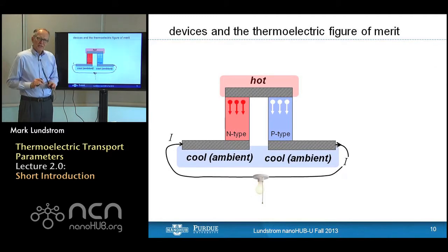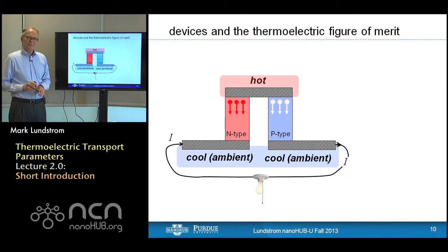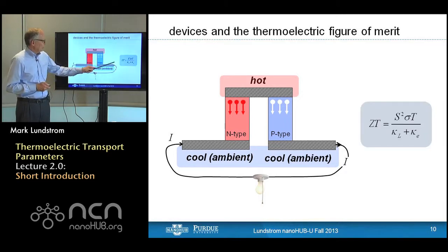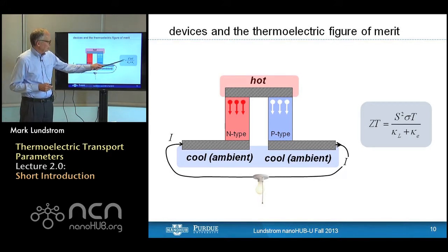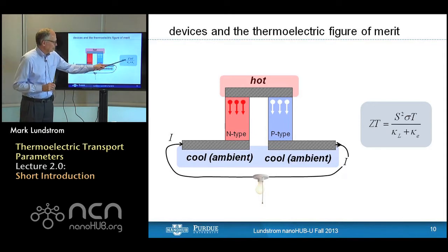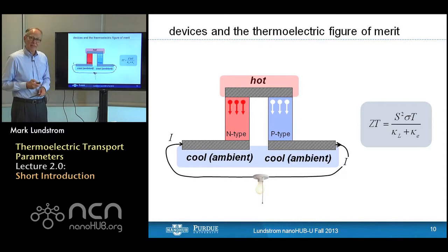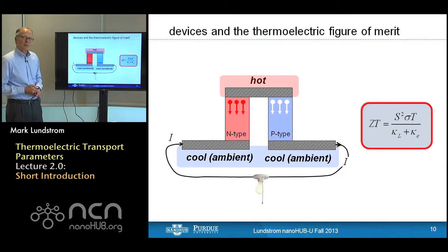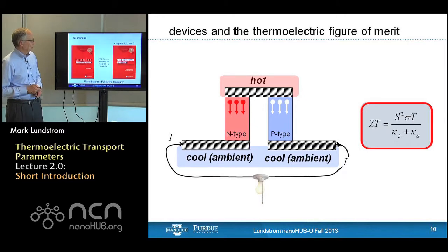Okay. Now, this week we won't have a lot to say about devices. Really, the goal is to set the stage so that we can analyze devices like this thermoelectric power generator. But we will talk about a very simple analysis just to point out that device performance is closely tied to a figure of merit ZT, which is dimensionless. And this figure of merit is key in selecting materials and structures that have optimum performance and simply depends on the transport coefficients that we'll be getting comfortable with this week. So we'll spend some time getting familiar with that figure of merit and what it depends on.